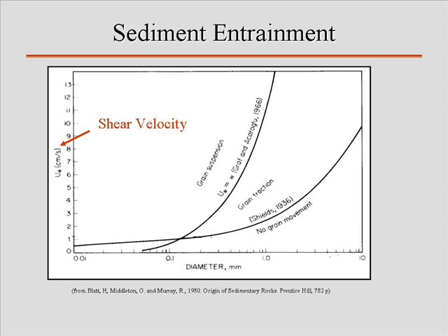You should also anticipate that as you get into finer and finer and finer grain sizes, it's going to level off, because it really doesn't matter if your particle is 1/100th of a millimeter or 1/50th of a millimeter. The velocities are going to be fairly similar. It doesn't take much to put particles like that into suspension.